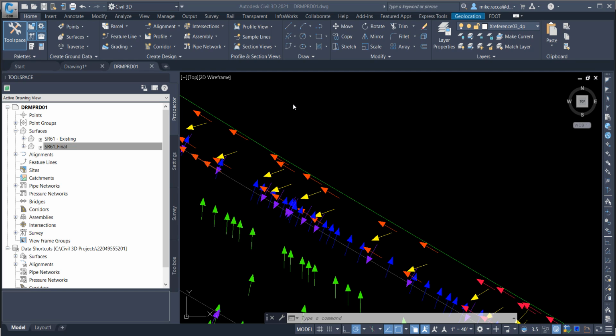Exercise 4.5. Define catchments using surface and water drop. The next steps will show you how to define catchment conceptually using a surface and the water drop command. The watershed analysis displays the same boundaries you make with the defined catchments from the surface command. It is a good starting point for delineating subbasins, which you will define later by creating polylines. Then use those polylines to create catchments that will then be assigned to inlets.